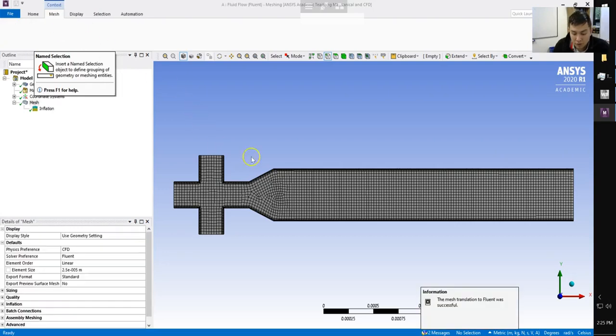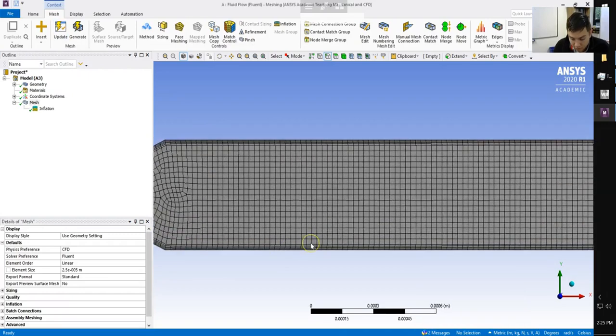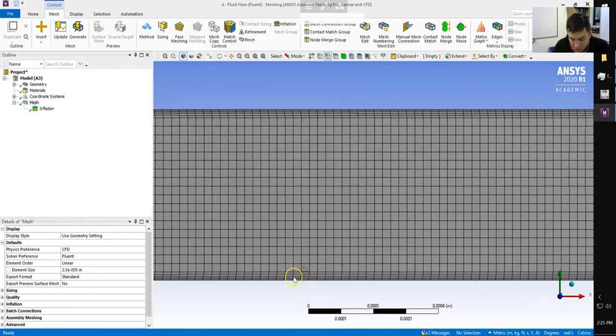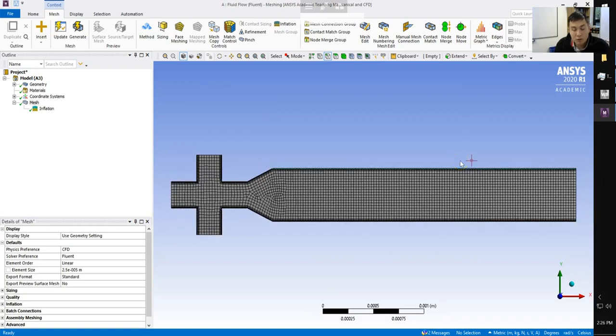Okay, and so you can notice we've got a higher resolution set of cells on the edge, and so we can zoom in a little bit and see how we have a high resolution, very thin, long cells at the edge, sort of form nice square cells in the middle, and then go back to long, thin cells at the top and bottom of the boundary. And this goes throughout our geometry. So that's all we're going to do with our mesh.